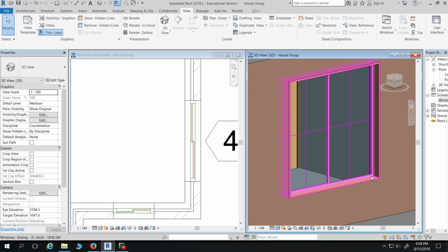At work, we have a brick seal attached in our window family. So for us, it's quite easy to tell, because it's a parameter. If the parameter's ticked for brick seal and you can't see it, the window's in the wrong way. It's a bit hard, but it does make sense.